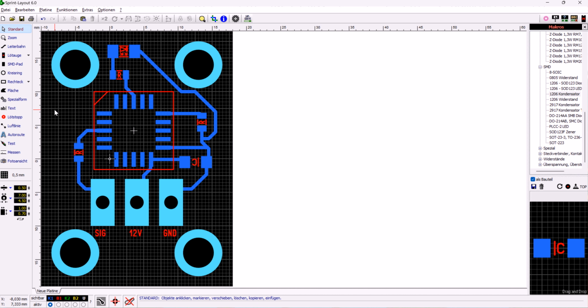And also most PCB manufacturers like it when you use ground planes, because they don't have to etch away so much of the copper, because the raw material for PCBs is epoxy, FR4 mostly, which is totally covered with copper. So everything where you don't want copper, they have to etch away. And the more they have to etch away, the more their etching bath gets saturated. So especially in the early days, and I think now too, PCB manufacturers like it when you use ground planes and they don't have to etch away so much copper. But for you as a user, the benefit of using ground planes is, of course, saving traces.